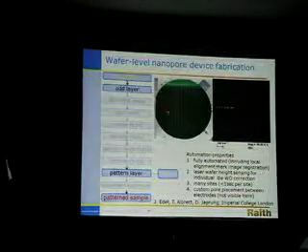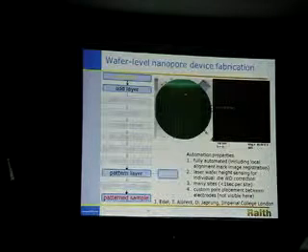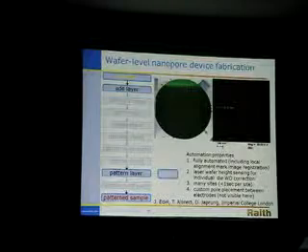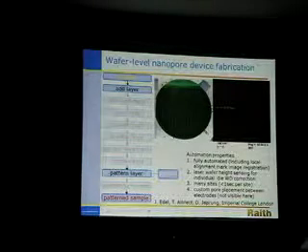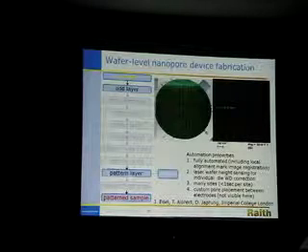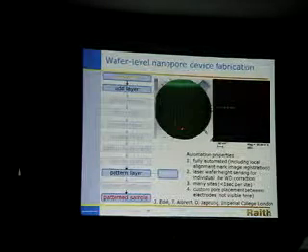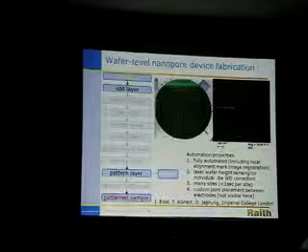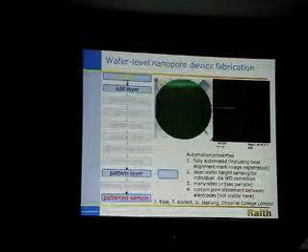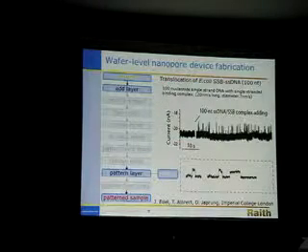And here you see nano devices, and the focused ion beam lithography system is very capable of putting nanopores in each device. And this whole process just took a few hours. This cannot be done with electron beam lithography, by the way. In fact, all of the examples that I'm showing you cannot be done with electron beam lithography.